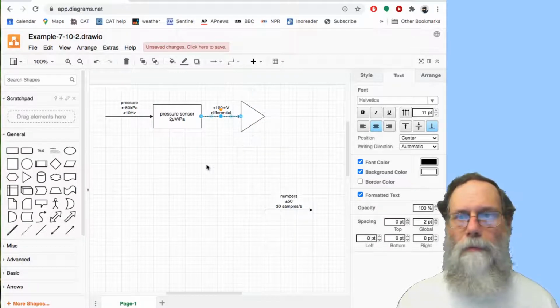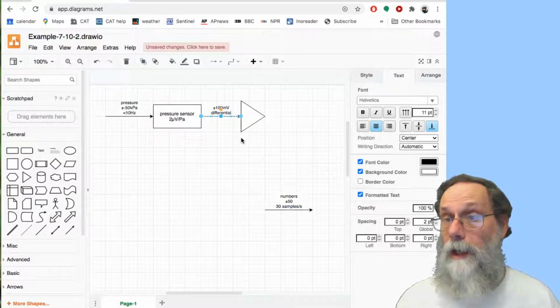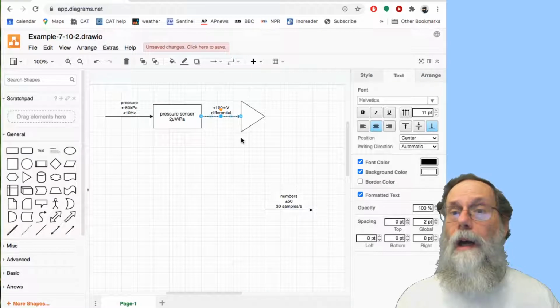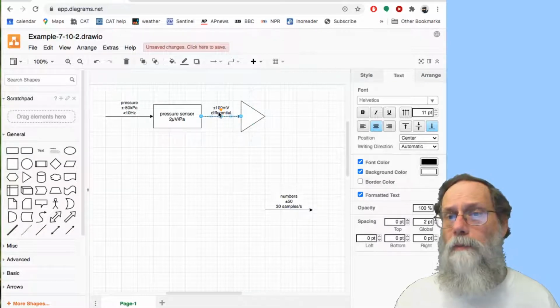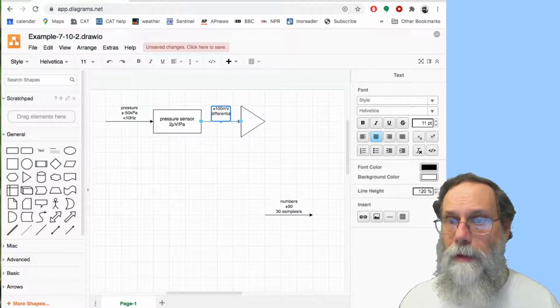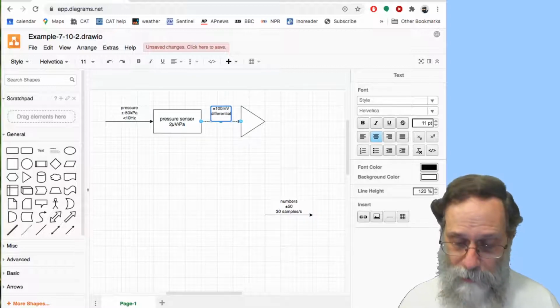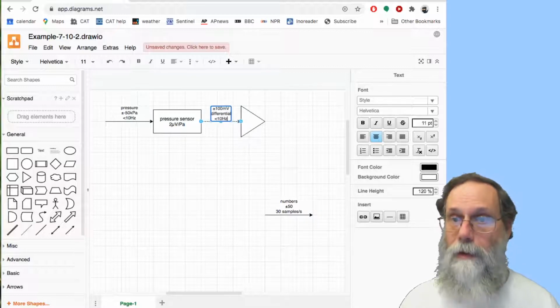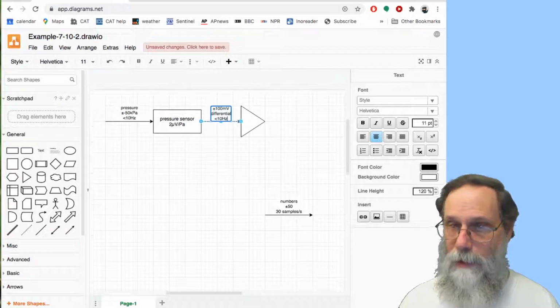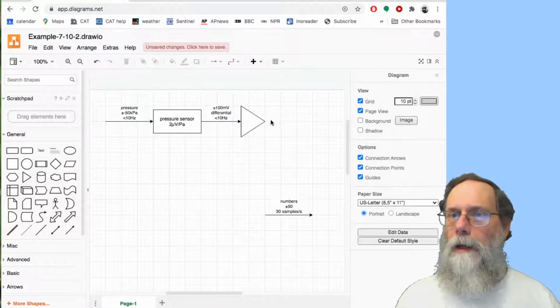Now, the amplifier is going to have a gain. I don't know how much gain. Depends what the output voltage is. I could also put one more thing on this one, because I do know one thing about this. Not just that it's a differential signal, I also know that it's less than 10 hertz. So I can keep that information here with the signal.